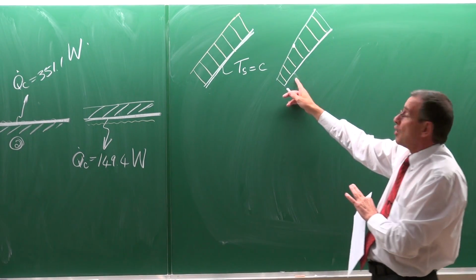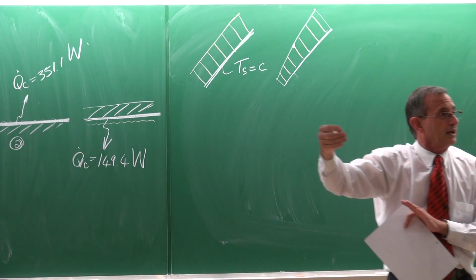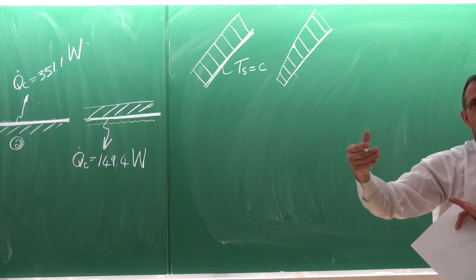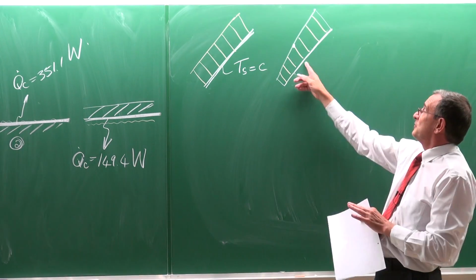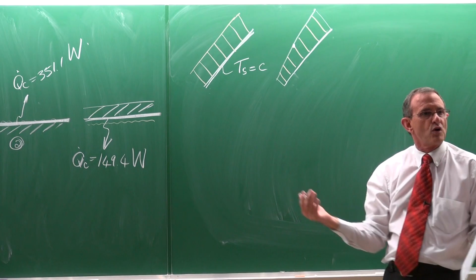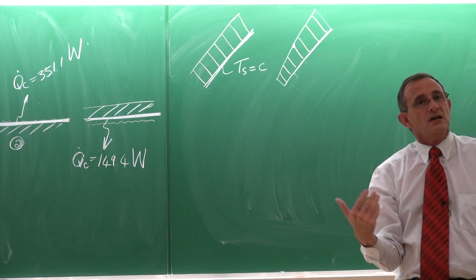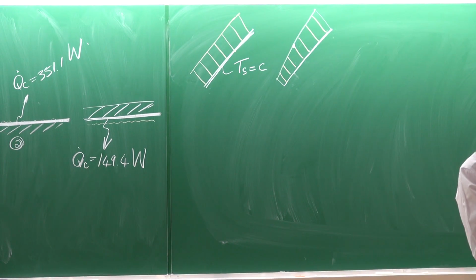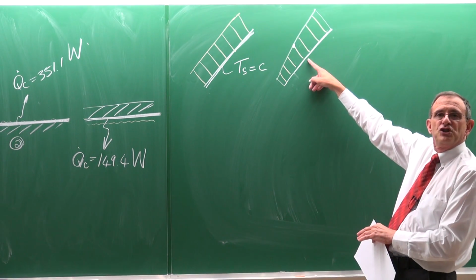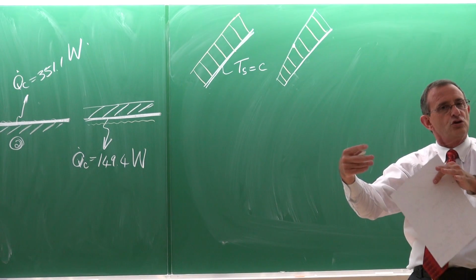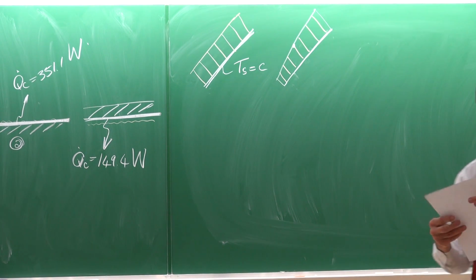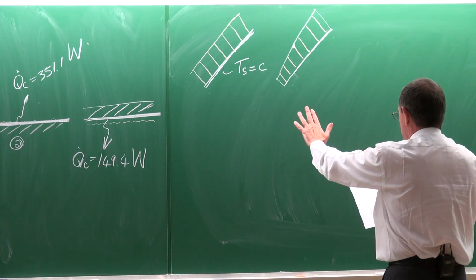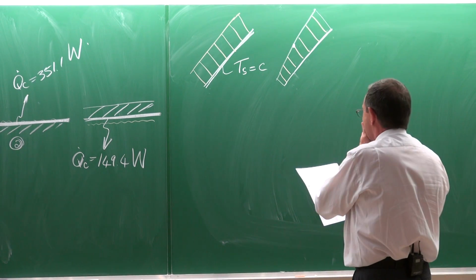When you're given a problem of a flat plate with a heat flux of 1 kilowatt per square meter, you don't have a surface temperature. So you have a problem getting the film temperature. As we've discussed previously, you guess one, and you have to go through all the calculations. Then you calculate the temperature there, and then you correct your iteration. That is something important to remember.